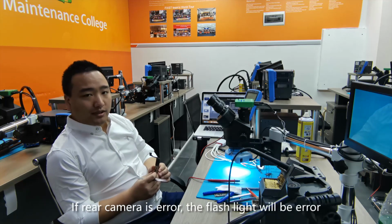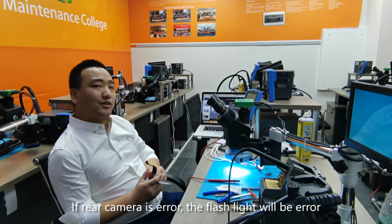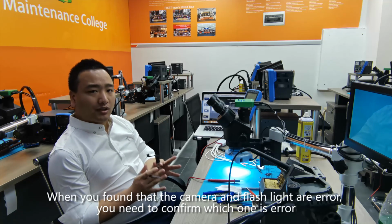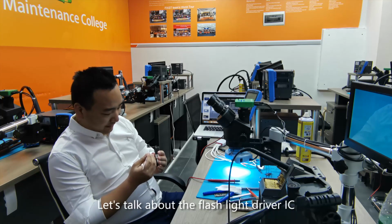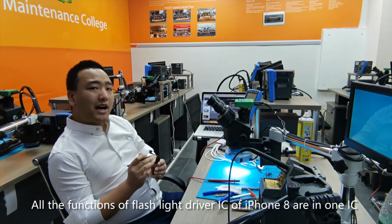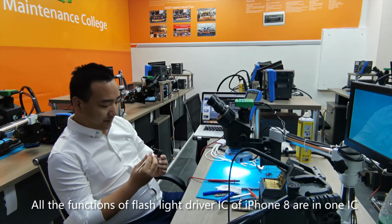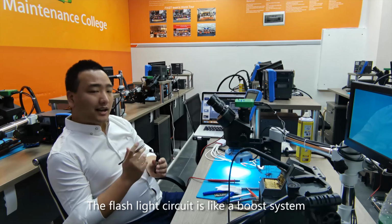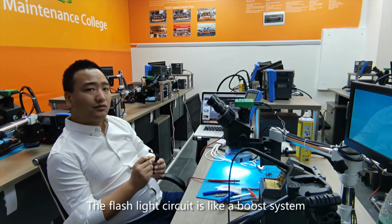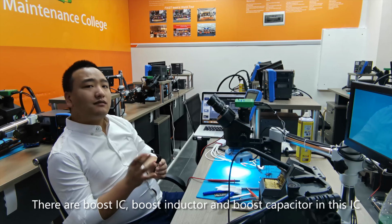If the rear camera has an error, the flashlight will have an error. When you find that the camera and flashlight both have errors, you need to confirm which one is at fault. Let's talk about the flashlight driver IC. All the functions of the flashlight driver IC of iPhone 8 are in one IC. The flashlight circuit is like a boost system. There are a boost IC, boost inductor, and boost capacitor in this IC.